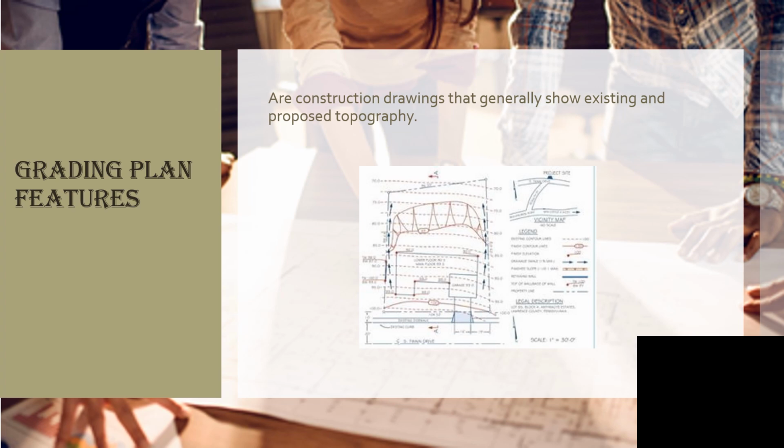Grading plan features. Grading plans are construction drawings that generally show the existing and proposed topography. The outline of the structure can be shown with elevations at each building corner and the elevation given for each floor level. As you can see on the screen, this is the detailed grading plan for a residential structure site.